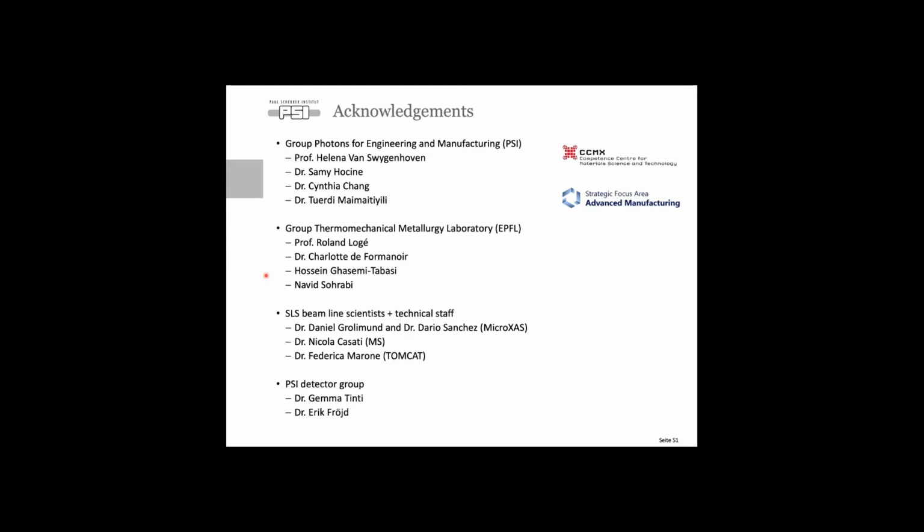So you said that you think this is a liquefaction type of mechanism. And what I have seen from the presentation is a combination. First you have a crack and then it remelts and extends. So I would say it's probably first there's a crack and then you have this liquefaction. Or do you also think that the cracks initially form by liquefaction? In other words, you have perfect solidification, no crack, and then only the remelting triggers the cracking.